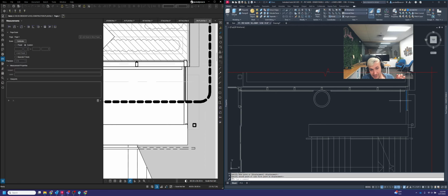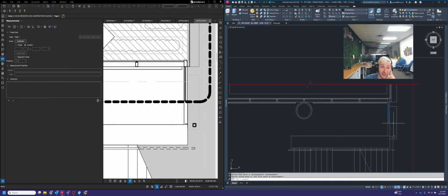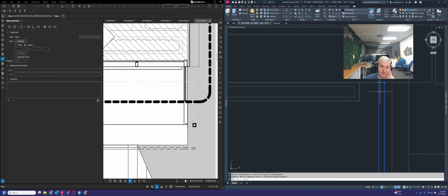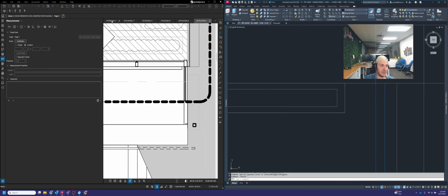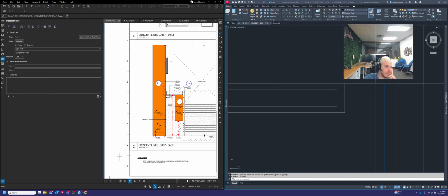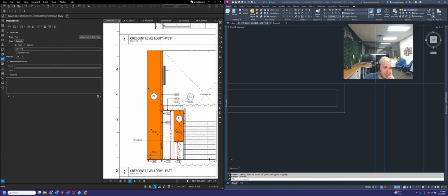Okay, so there is one thing that I kind of forgot to do when we were talking about elevation views, and that is we do have full depth reveals that we need to add whenever you have a panel that meets a wall. So in this case here, although it's not shown on the architecturals this way, it is a company standard that if you have a panel that butts into a wall, you really don't want to just leave it as a joint where the panel butts to the wall, because that means you have to scribe the entire side of that panel, and that's a real pain to do in the field. You can imagine trying to make sure that panel is flush with that wall. Wall is probably kind of curved.